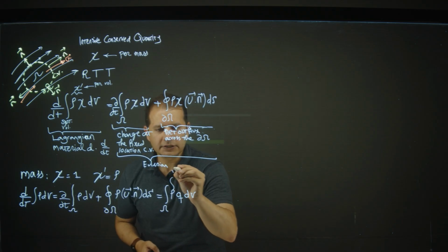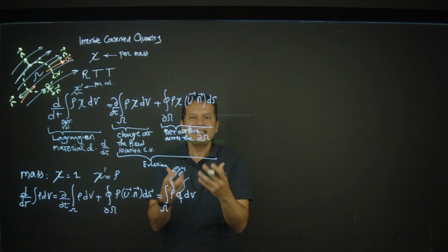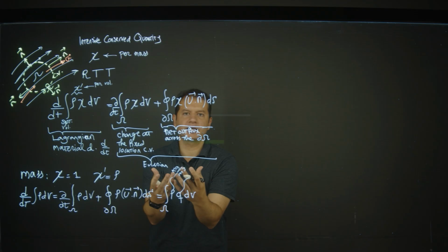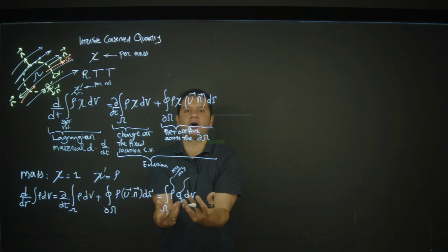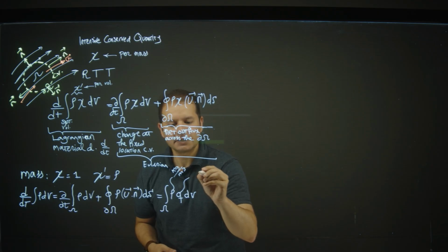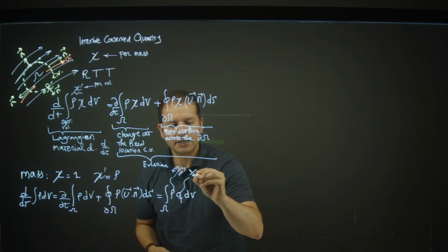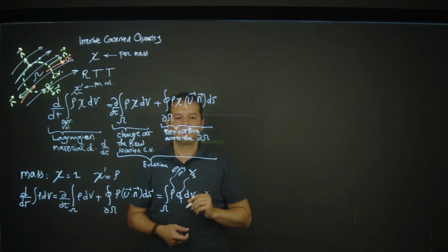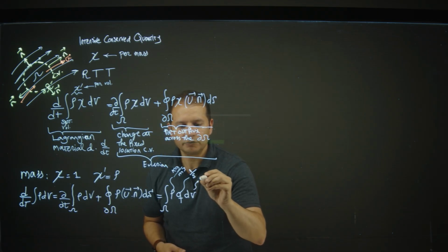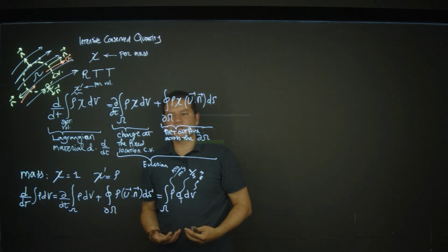This rho is kilogram per cubic meter, and my Q is the intensive Q, which is the volumetric production rate over volume. So that will be 1 over second, and then I have here d volume, which is cubic meter. Q dV is the volumetric production that I have.